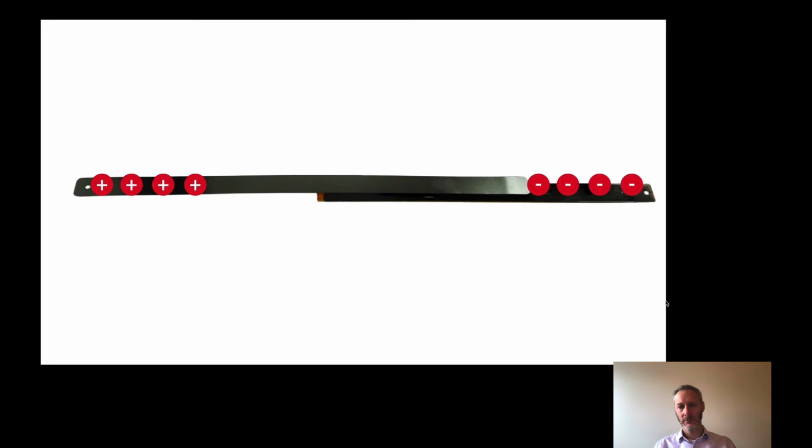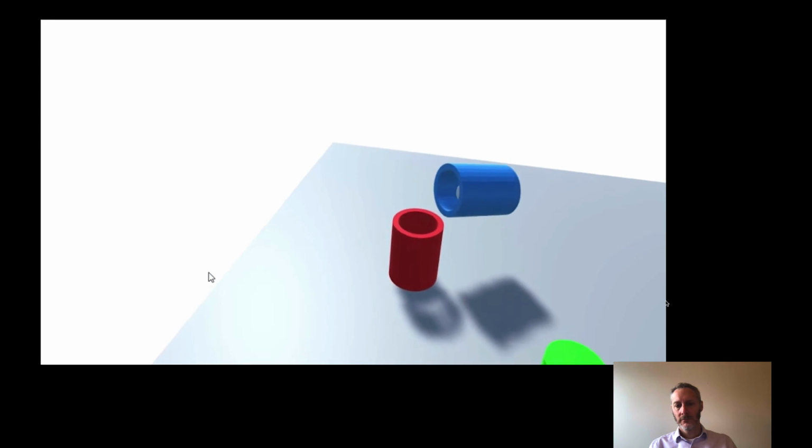So the way it works is that we have 2 metal strips on each finger, and they normally can slide very easily, allowing the fingers just to move very naturally without blocking the motion. However, as soon as we apply voltage between the strips, in a few milliseconds, they're blocked together, and that prevents the user from then closing his hand. We have up to 40 newtons of force per finger, and that means we can generate sensations of holding a very, very hard coffee cup, but also something soft like a sponge.